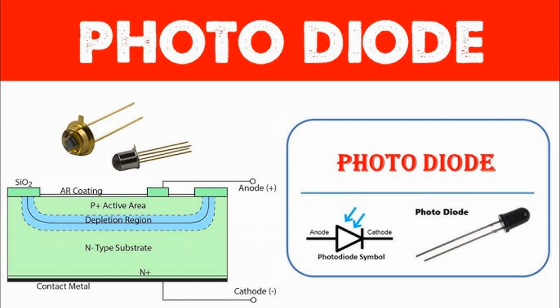6. Barcode scanners. Photodiodes are used in barcode readers to detect the reflected light from the black and white bars of a barcode. The differences in the reflection intensity are converted into electrical signals to decode the information in the barcode. 7. Position and proximity sensing. Proximity sensors. Photodiodes are used in devices that detect the presence or absence of objects by measuring reflected light.